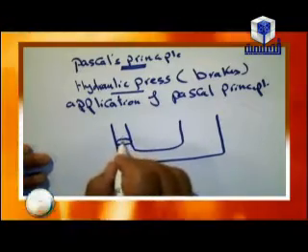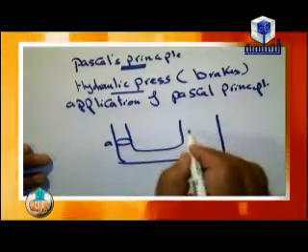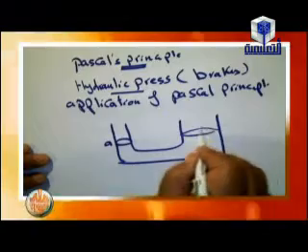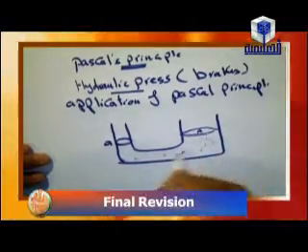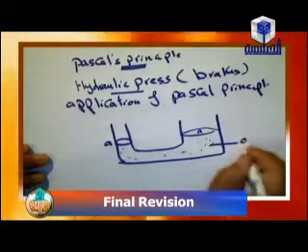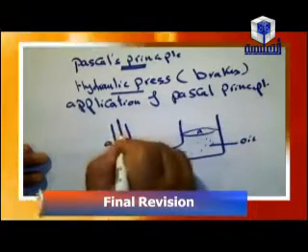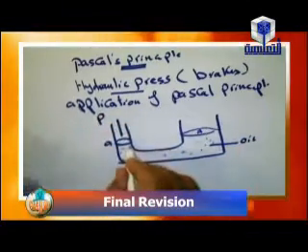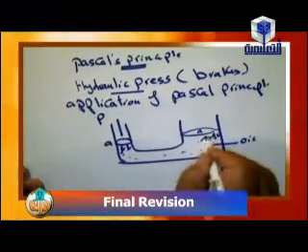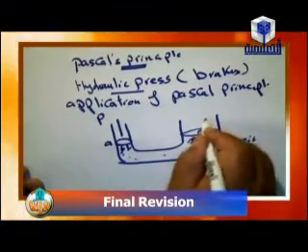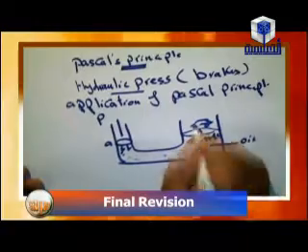The first is a small piston and the second is a large piston. The liquid, suppose oil, is confined between them, and if we apply a pressure on the small piston, this pressure will be transmitted to the large piston, and we can carry any heavy load on the large piston.